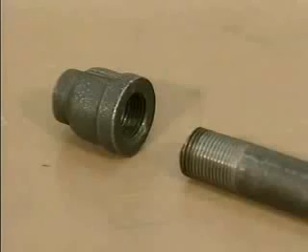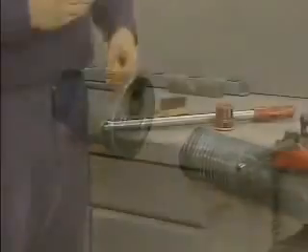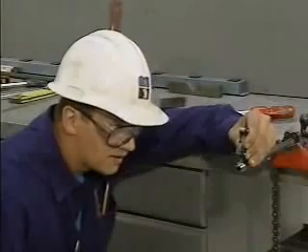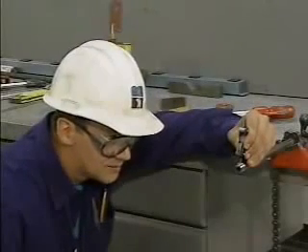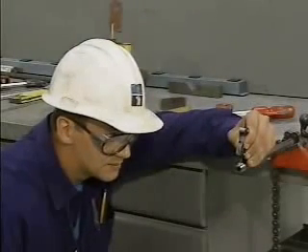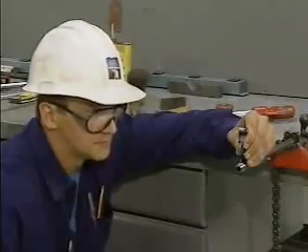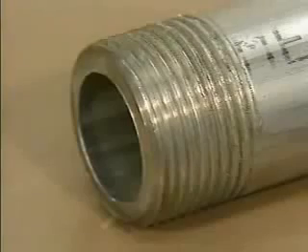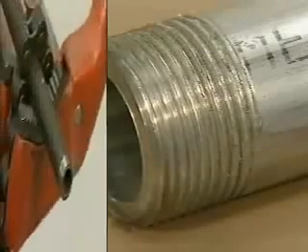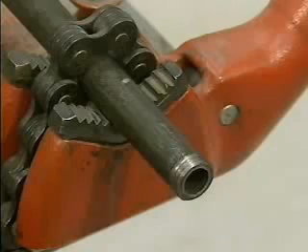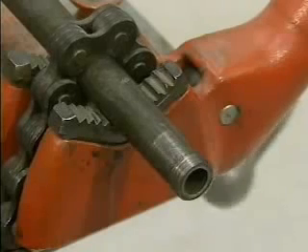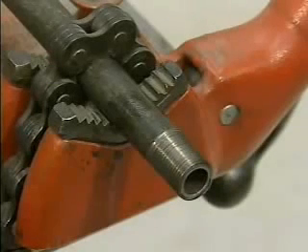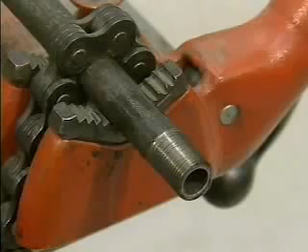The pipe die you use must also cut the correct number of threads per inch, or else the pipe threads will not match the threads on the fitting. You can use a thread gauge, such as this one, to calculate the number of threads per inch on an existing pipe or fitting. The final consideration when you're threading a pipe is the length of the threads. Threads that are cut too short will be weak at the joint and will leak. Threads that are cut too long will make creating a joint difficult, which may also cause a leak.